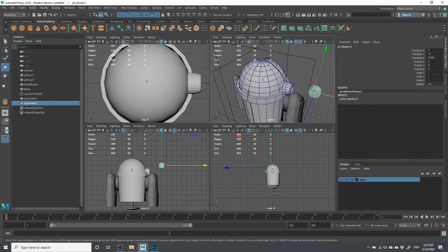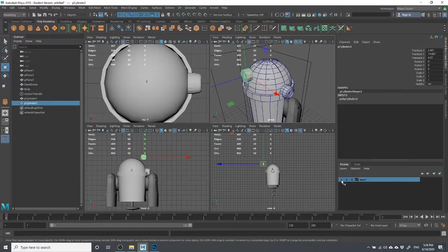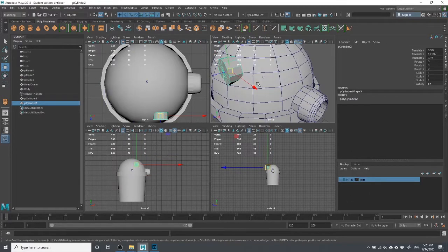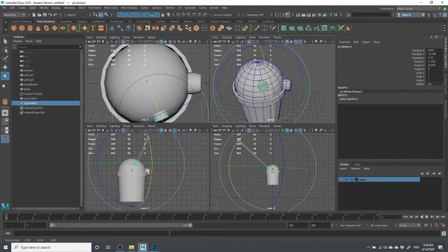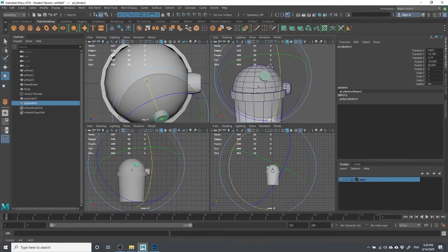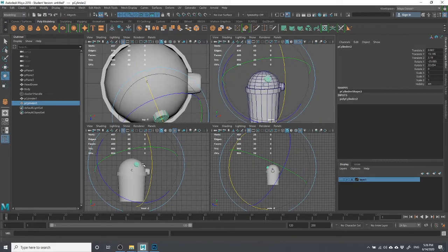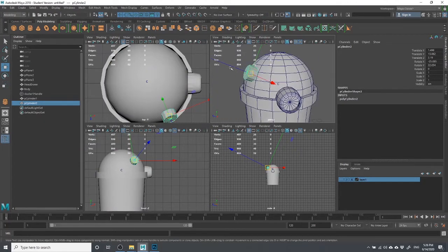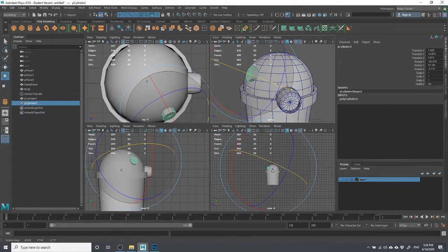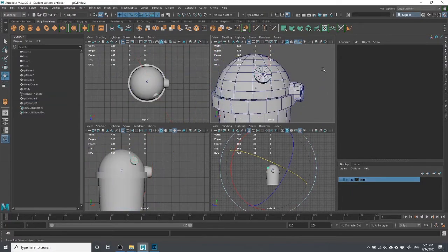All right, so here I'm going to use that trick that we were talking about to position these eyes. I'm going to press V to snap to vertex. I'm going to find a vertex that I want to snap to. So maybe, whoops, let's get rid of this. I'm going to press V and just snap along one of these things, and we can have it arranged like this to that side. So if we want to think about where this eye is, you position it where you want, like that. Just make sure that when you do that, you remember where this thing is.